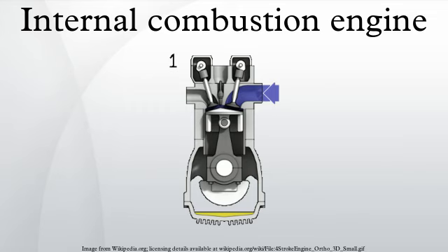The Scuderi engine addresses the breathing problem by reducing the clearance between the piston and the cylinder head through various turbocharging techniques. The Scuderi design requires the use of outwardly opening valves that enable the piston to move very close to the cylinder head without the interference of the valves. Scuderi addresses the low thermal efficiency via firing ATDC. Firing ATDC can be accomplished by using high-pressure air in the transfer passage to create sonic flow and high turbulence in the power cylinder.